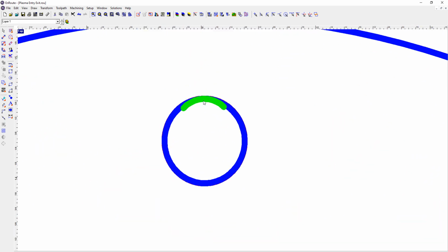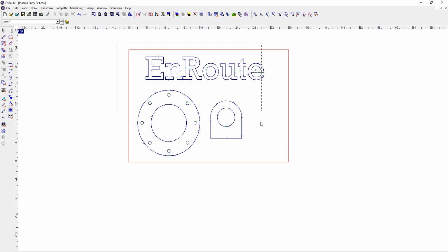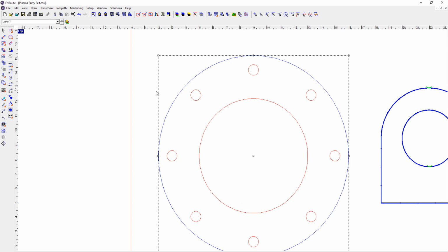Now let's say that instead of doing this arc circle, you wanted it actually to be a straight line that's going to cut in a perpendicular motion into the part and then travel around. And I've seen that done in various places and heard that's a recommendation for doing inside circles. So if I select just this shape now, let's delete this toolpath and concentrate on this one.